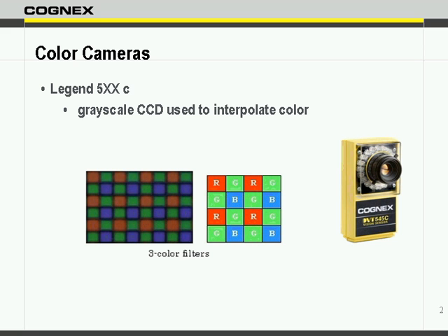on that particular pixel. So that means that when you see something like what we're seeing here, this three color filter, we see that a particular pixel only gets from the original image, from the scene, one of the three values, red, green, and blue. So the other two must be interpolated or calculated from the neighboring pixels that obtain a value of that other color that's missing for that pixel.